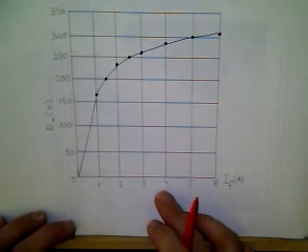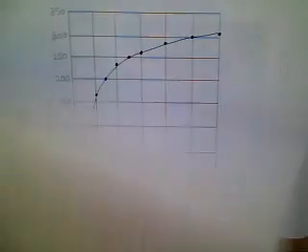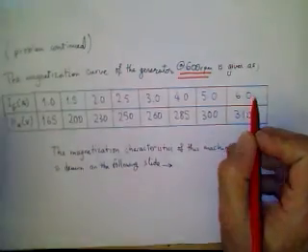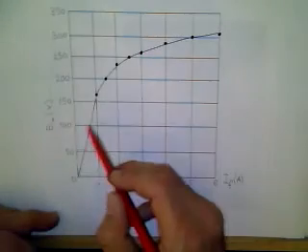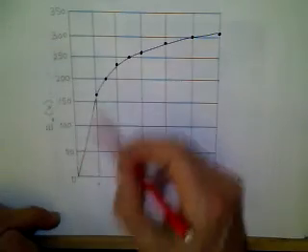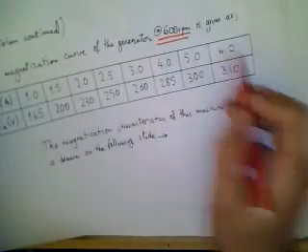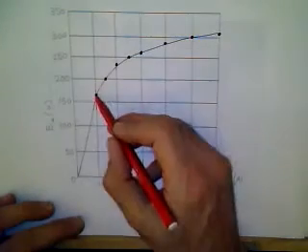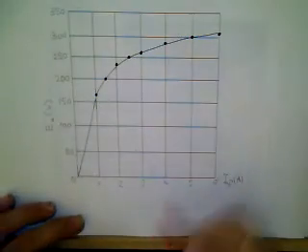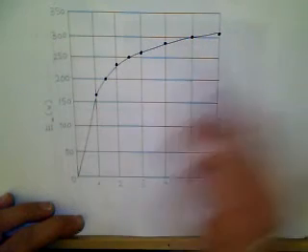This is the magnetization curve; the horizontal axis is the field current, and the vertical axis is the induced voltage, with units of amperes and volts respectively. We have 8 different value pairs, shown with thick dots in the magnetization curve. So we have an almost linear region and then a saturation region.